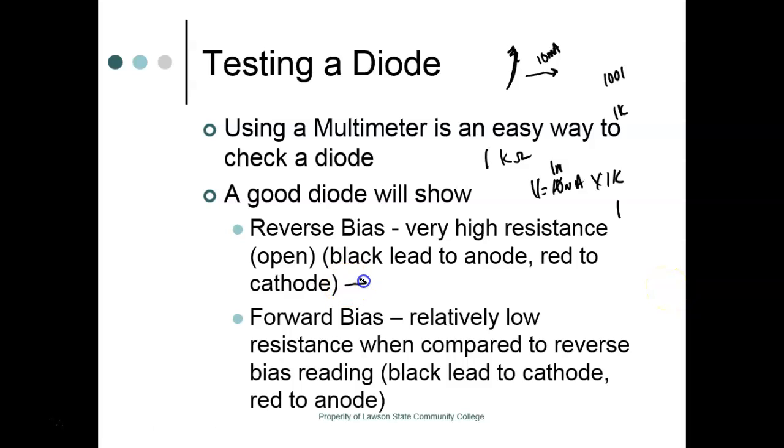So if you have questions, you need to ask them. I think on my meter, it measured overload when it was reverse biased, and it measured 1.2 megohm when it was forward biased. Now, how do we forward bias it?